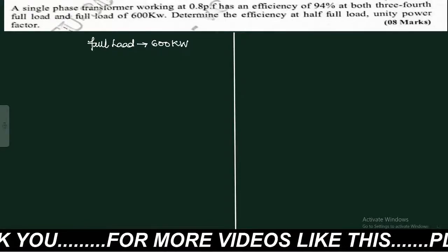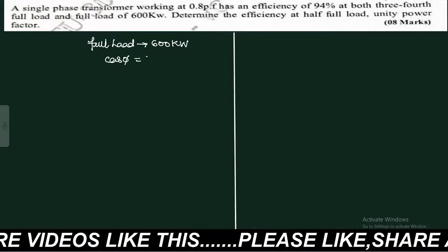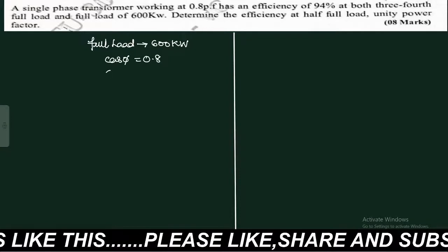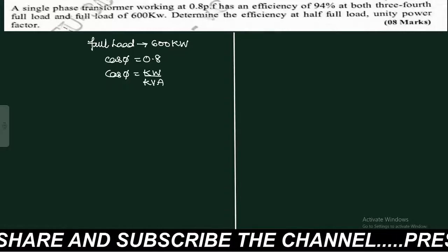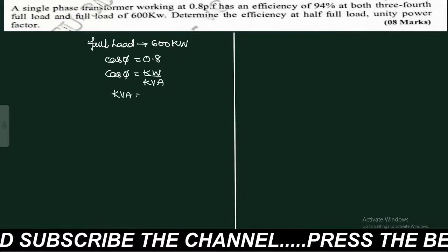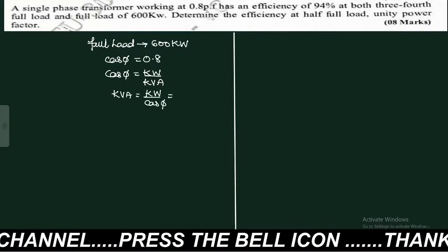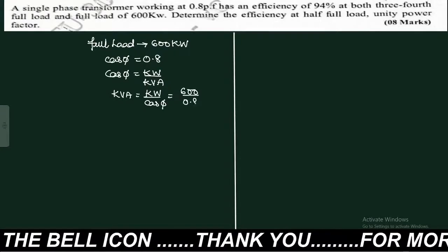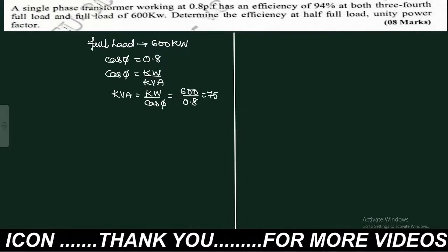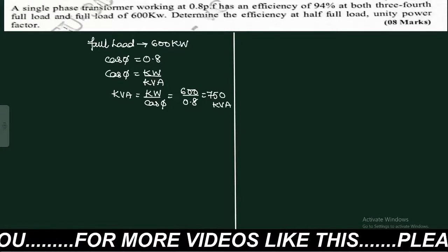The power factor is given as 0.8. We already know the relation that power factor is kW by kVA. Let us find the full load kVA, that is the kVA rating of the transformer, which is kW by cos phi. Here it is 600 divided by 0.8, and you get 750 kVA. So this is the full load kVA of the transformer.